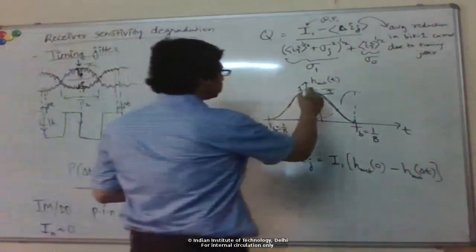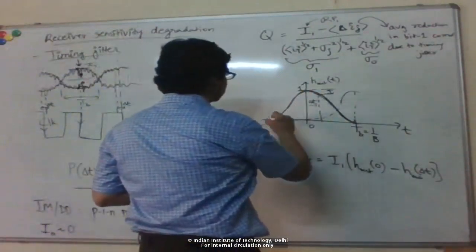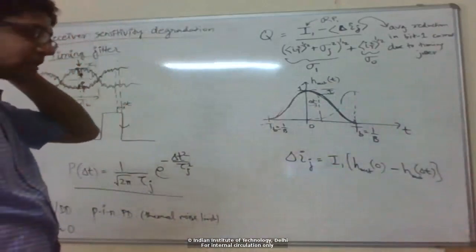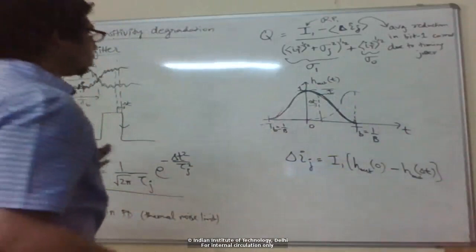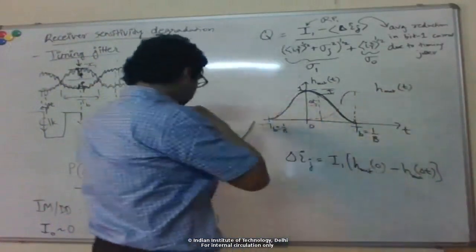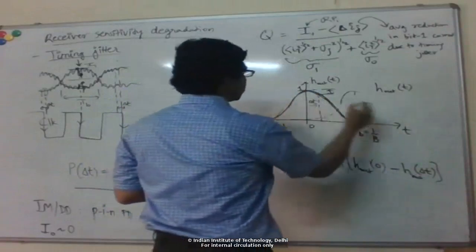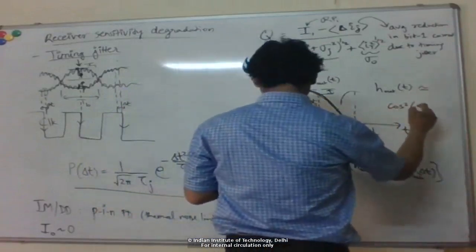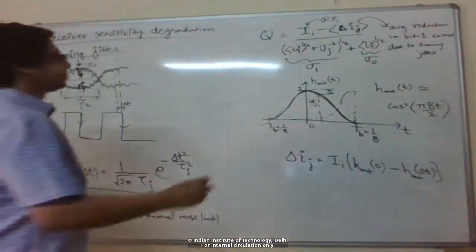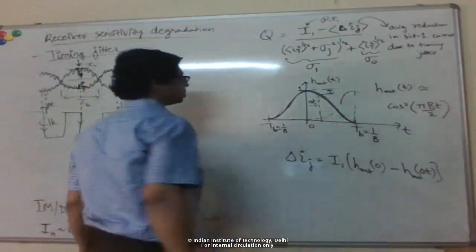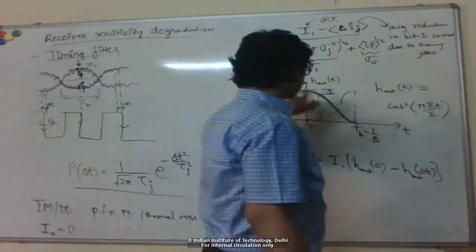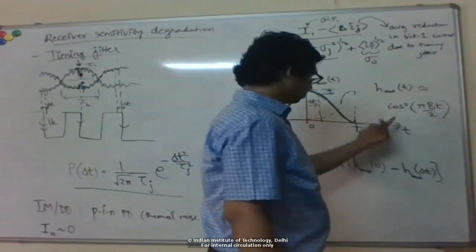Okay, so this exact pulse shape that you get again depends on the kinds of photoreceiver circuits and filter circuits that we use, which we had discussed briefly a few classes ago. One convenient pulse shape to assume is a cosine squared. That's a reasonable approximation to the pulse shape you get, and it also makes the calculation tractable.